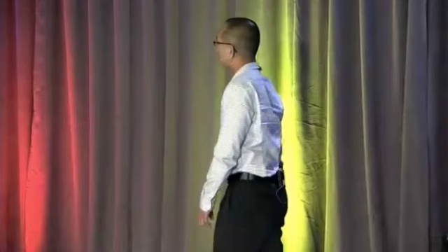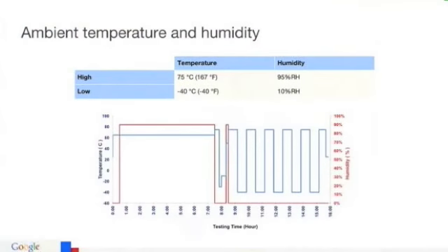Next up are environmental specifications that relate to effects on the modules, starting with ambient temperature and humidity. The MDK currently provides this table and lists them as operational limits for the prototype modules. That is strictly not correct. These numbers actually correspond to the maximum range for an accelerated aging test using this thermal cycling profile you see here. They are not meant to be operational limits.